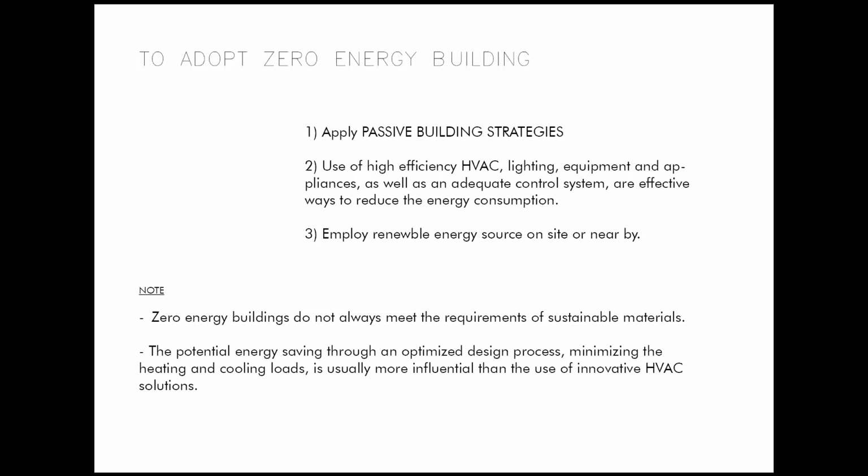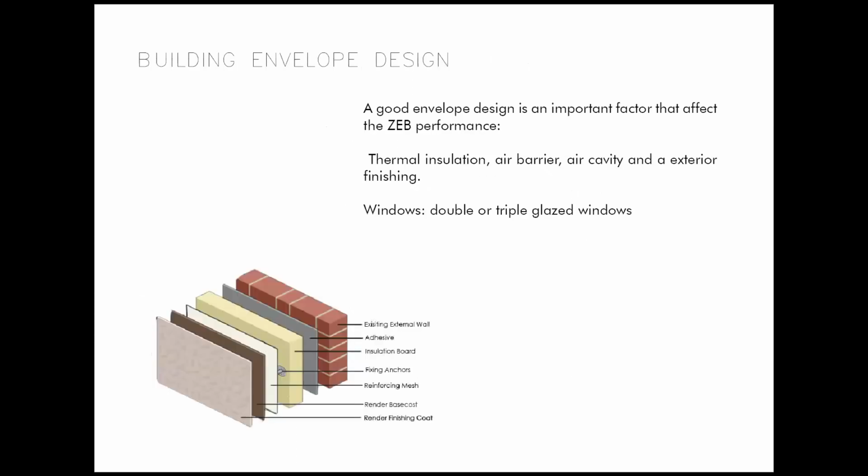The potential energy savings through an optimized design process that minimizes the heating and cooling loads is usually more influential than the use of innovative HVAC solutions. Then it's very important in our zero energy building design to take advantage of the passive strategies. As I have told before, it's important to think about the building envelope design, because having a good envelope is an important factor that affects the building performance.